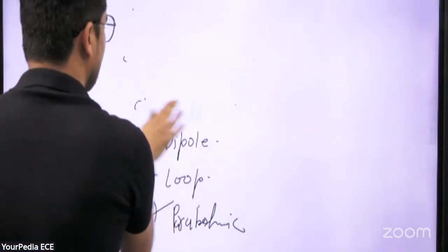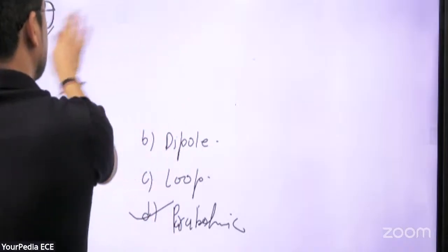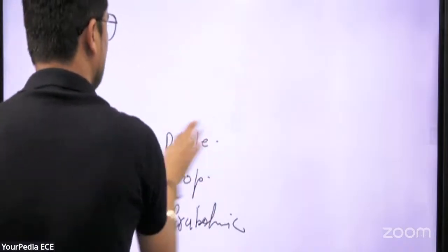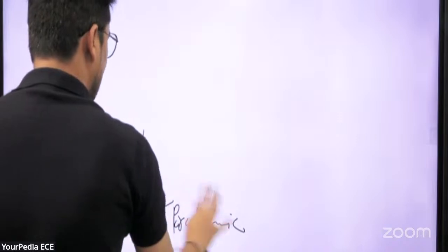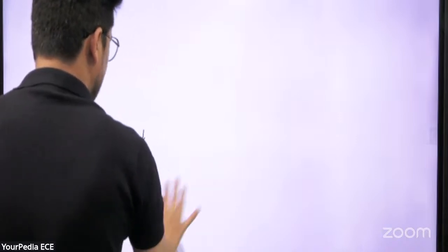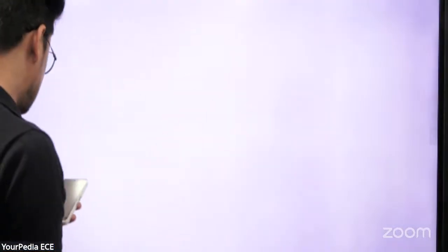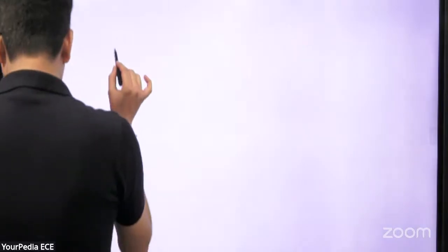Radar is sending an EM wave towards the object, and when that EM wave reflects from that object, it will receive that one, and it can predict the distance between the radar and the object, and the speed of the object on the basis of that one, right? After how much time it will receive back that signal. So basically that is how the radar detects the object.